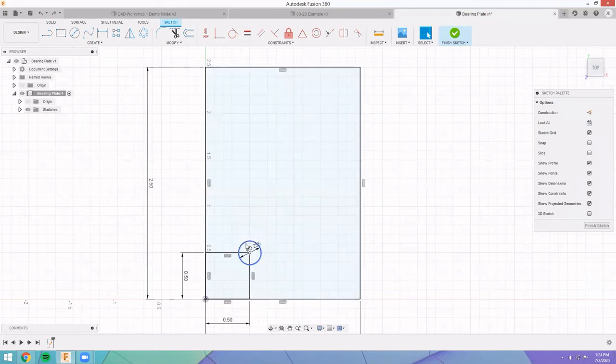If we said we wanted to take this hole and have this hole exist on the right side, and no matter what we do to this one, if we move it left or up or make it bigger or smaller, we want the one on the right to do the same thing. What we can do is basically mirror this hole onto this side. And the only setup you have to do for a mirror is give it a line or a plane that it's going to mirror itself over.